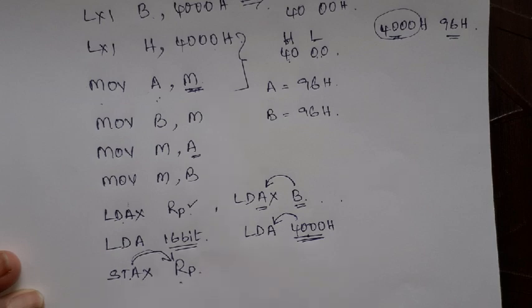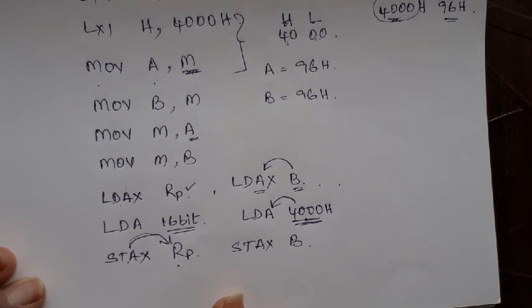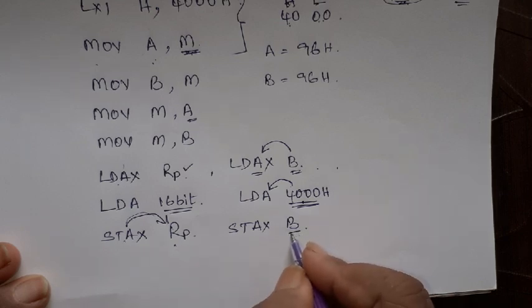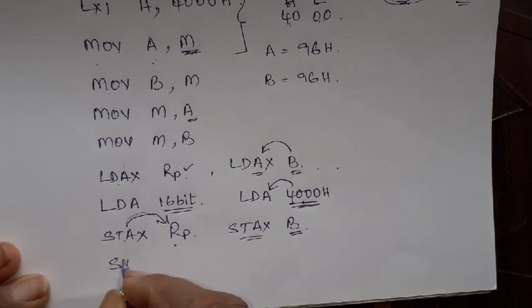the memory location. So here if I say STAX B, whatever contents are there in accumulator will be copied to the memory location whose address the BC pair is holding. BC pair is holding an address of a memory location. So to that memory location, the accumulator contents will be transferred. So that is STAX, store accumulator.